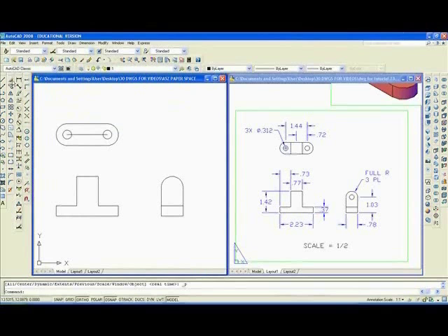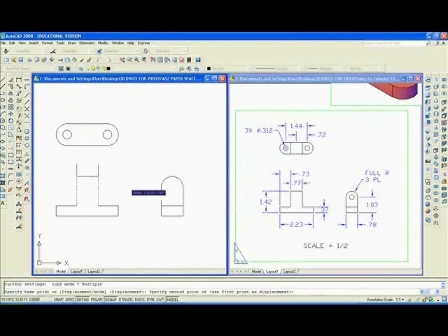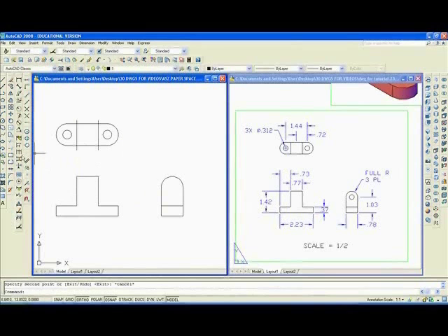I want to erase that line, copy the 2 vertical lines, move them up, escape, TR enter to trim from both of these lines. Try it again. Trim from both of these lines, but the parts that stick out.